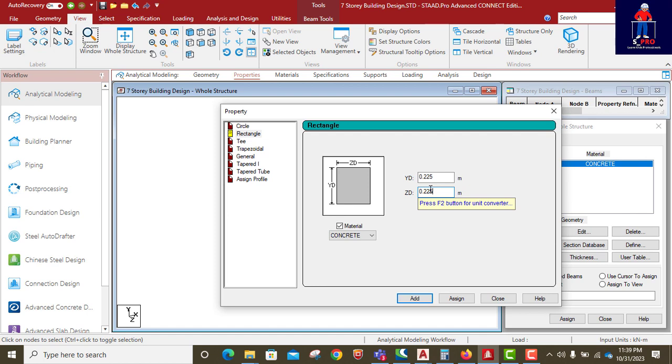Whatever is happening at the roof level is being transferred to the seventh floor, and whatever is happening at the seventh floor plus the one at the roof level will be transferred to the sixth floor. The seventh and the roof level plus the sixth floor will be transferred to the fifth floor. So just like that, they get to the ground floor, to the ground. So the members at the ground level carry more load. They are the members bearing the compression.